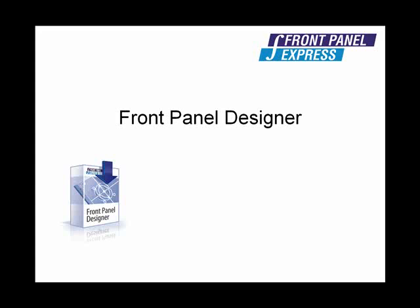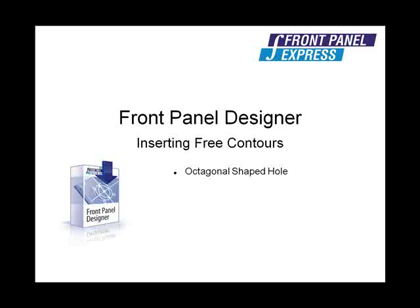The free contour tool is used to create a non-standard shaped hole or cavity on a panel using DXF imports. In order to insert a non-standard shape onto your panel, you need a single closed contour in a DXF file. In order to demonstrate how to use the free contours tool, I will create an octagonal shaped hole on our sample panel, followed by a star-shaped cavity near the bottom of the panel.